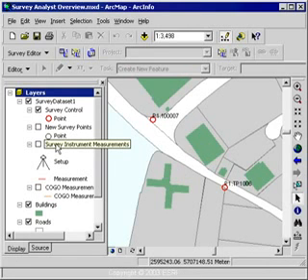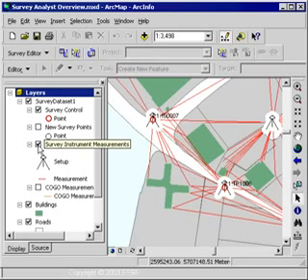The process would be, if I wanted to improve the quality of those building footprints, or any feature in those layers, surveyors would go out in the field and set up an instrument, and they would conduct measurements at those known locations. And now you see the measurements reflected on the screen. What you're actually looking at is an instrument setup and measurements. Those red lines represent the measurements that were conducted.